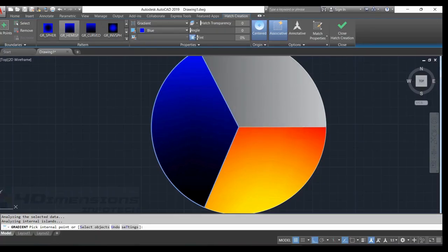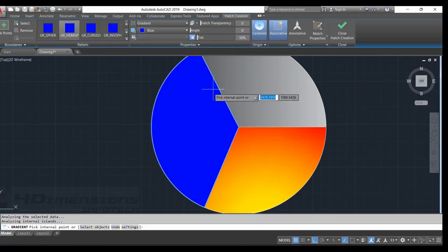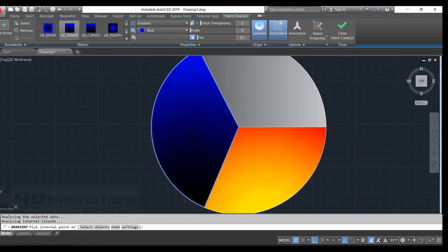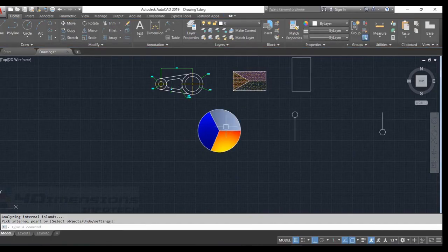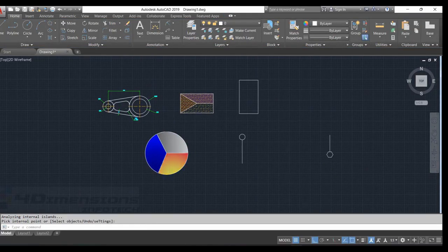If I want to adjust the tint, you just need to drag it here. We can see the percentage of the tint to be shown can be adjusted by the value given. So I'm going to take 50% here. So it is taking complete blue color now. You can increase or decrease this number. I'm going to say 25% only. So here the tint is 25%. We can see the appearance here. Say close creation. So in this way we can apply the gradients and hatching.